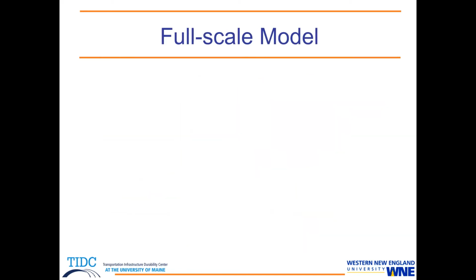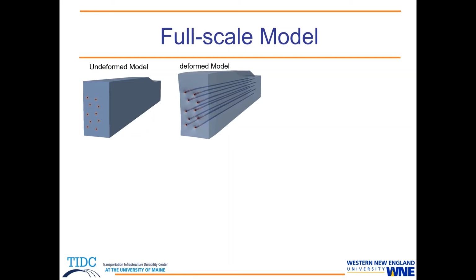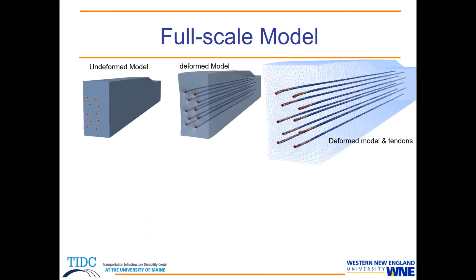Abdullah? Hi everyone, Abdullah here. Recently, with the help of our in-house code, we performed a study on the high-performance computer to identify the role that indentation size and shape on prestressing wires play in the mechanical interlocking. For that, we made 3 different full-scale models of concrete cross ties embedded with different wire types: the WA wire, the WG wire, and the WP wire. With these models, using our in-house code, we performed prestress simulations on the high-performance computer.